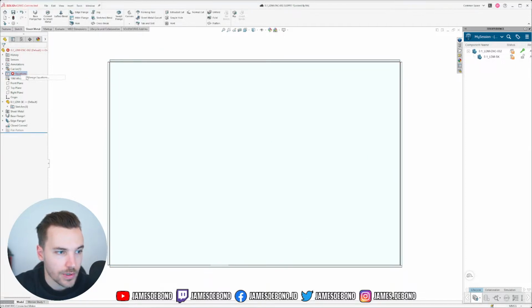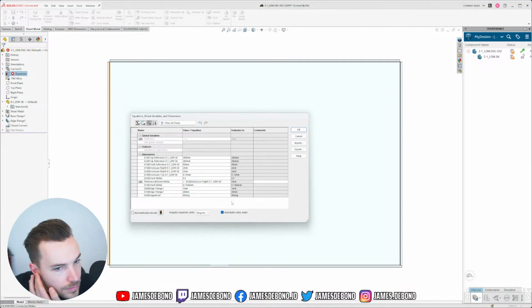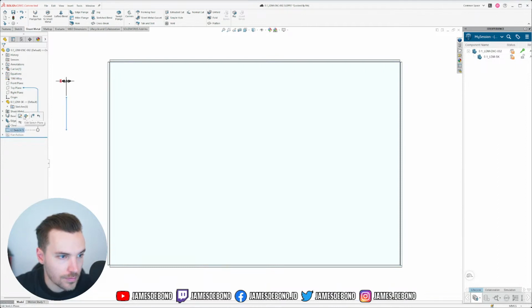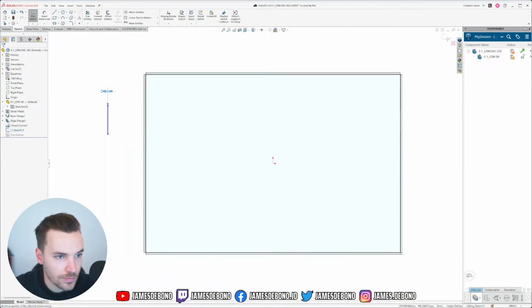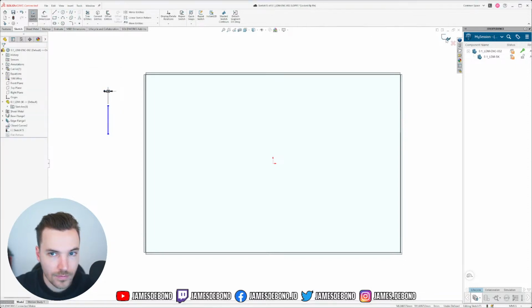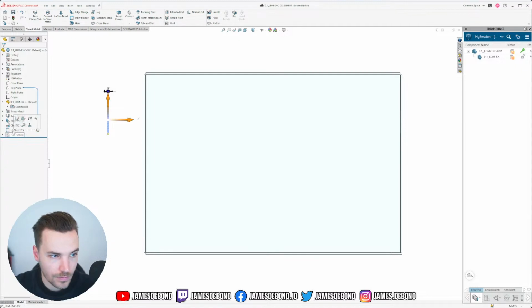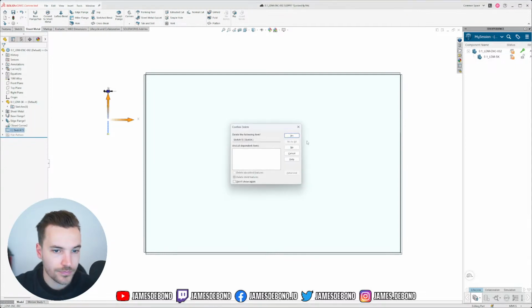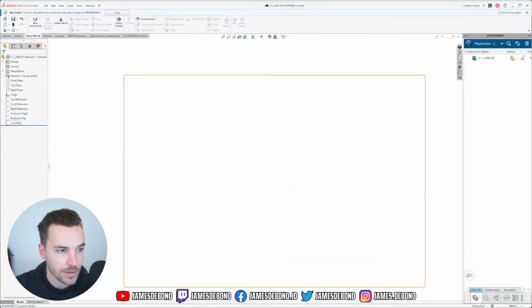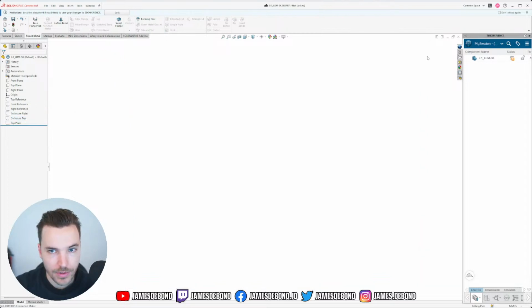Come on, there is no equation there. So at least I can have this in my sketch that I'll just have a 0.1 millimeter gap. I'm gonna have to just match that until SolidWorks changes something.